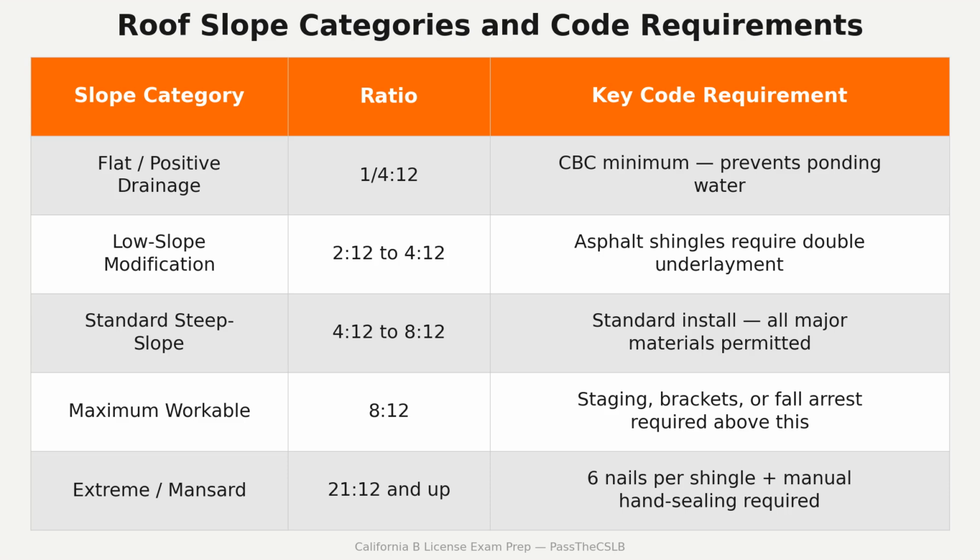That fire, and others before and after, drove California to create what are now very high fire hazard severity zones and to write California Building Code, Chapter 7A alongside Health and Safety Code, Section 13132.7. The language of those sections is precise. Wood shakes and shingles are prohibited in designated very high fire hazard severity zones. Not restricted, not conditionally permitted, prohibited.